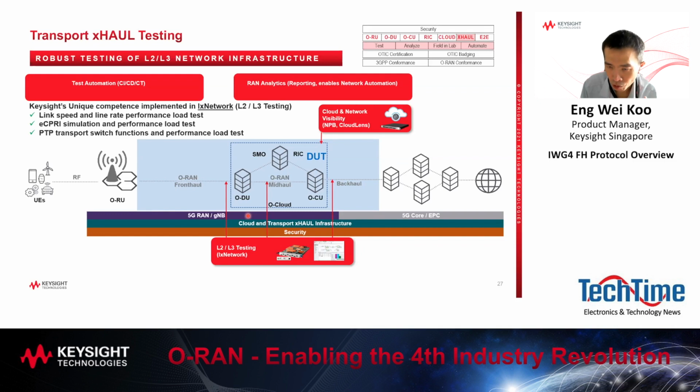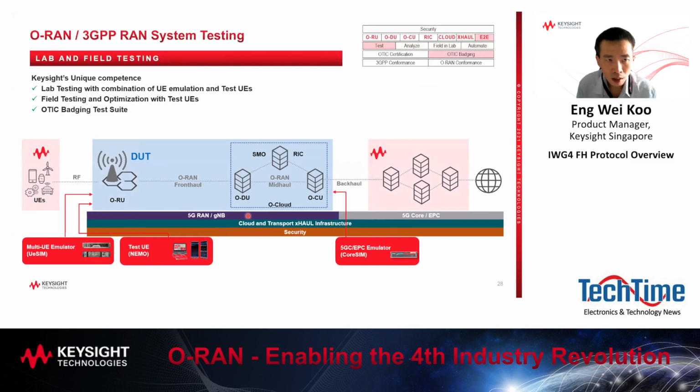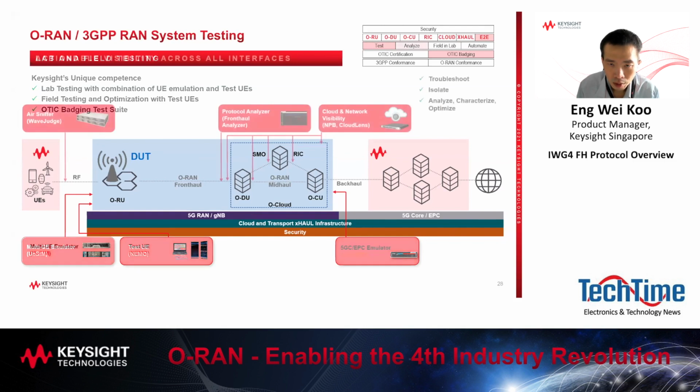If you remember, especially for the LS-C2 and C3 and C1 configurations, that needs to be tested because the PTP signals are basically transferred across the open fronthaul interface. And from these slides, I will just skip them, because the same methodology and the same tools will be applicable for end-to-end system tests as well.